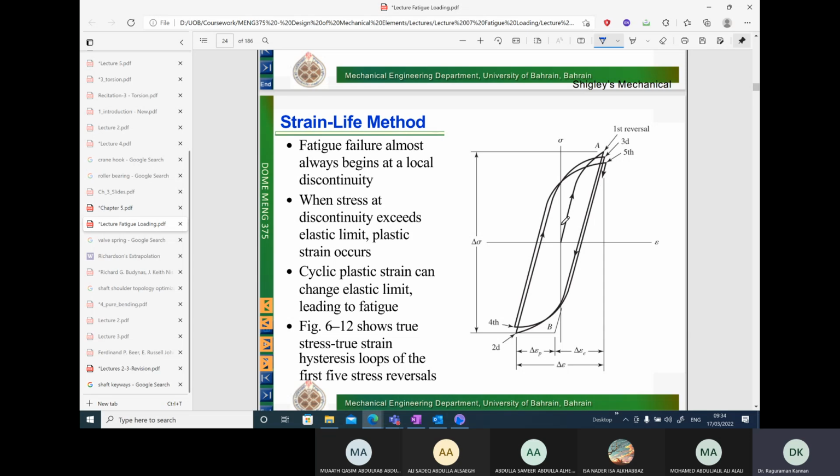There is some strain hardening phenomena because we have reached the yield point. Once we cross the yield point, we know that after one cycle, again the yield point will keep on changing. Every time I do cold work on the specimen, the yield point will change, and because of that, the curve is going to change at each point.